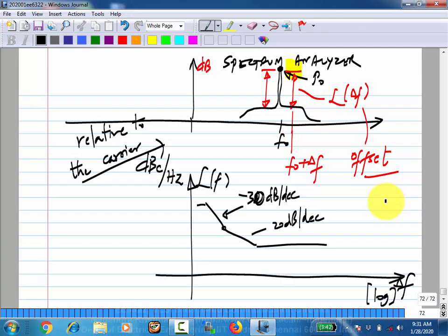So now we have looked at the basics of noise. I think whatever we have done so far is good enough for us. Essentially, you need to know the variance of noise to find the bit error rate, both in the y direction, in which case you may have a voltage noise that is added to your signaling voltage, or in the x direction where you have a jitter added to your clock or the signal itself. I assume that the clock is jittery, but the data transitions also can have jitter, right? Because it is generated from some other clock in the transmitter. So that also will have the same effect.